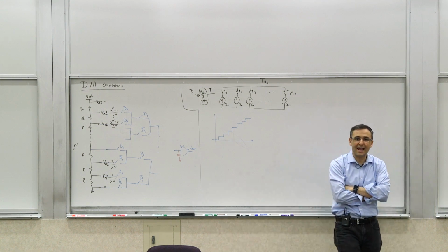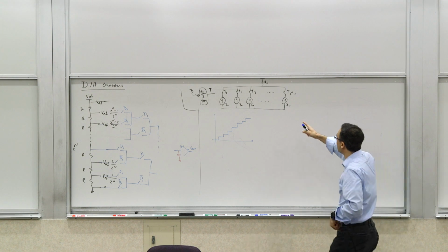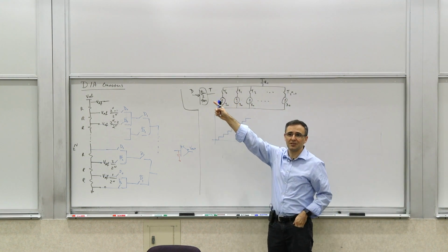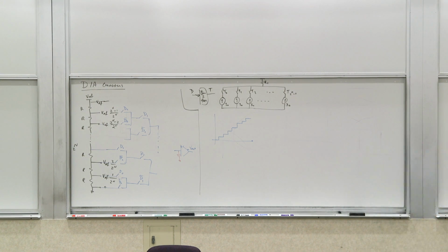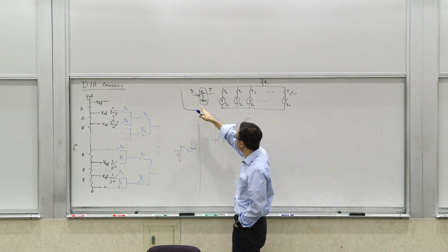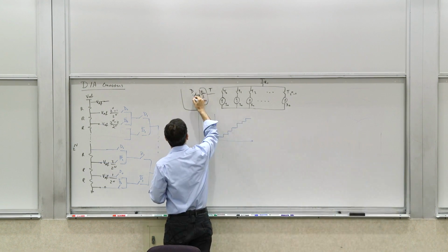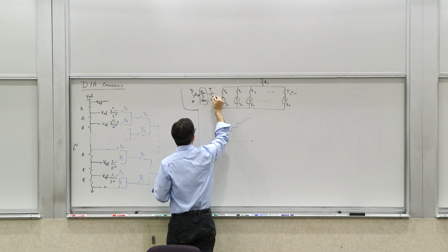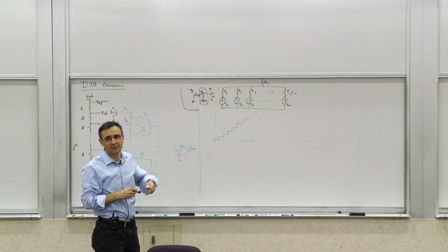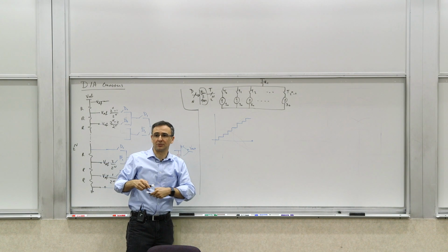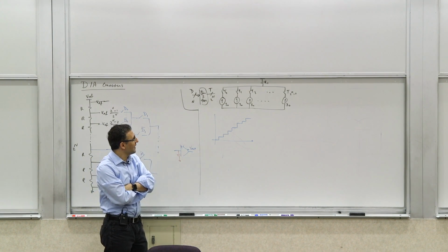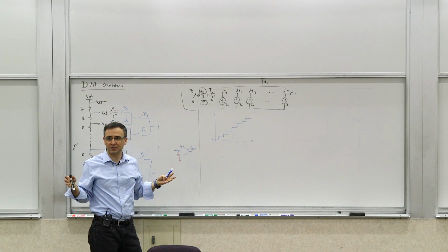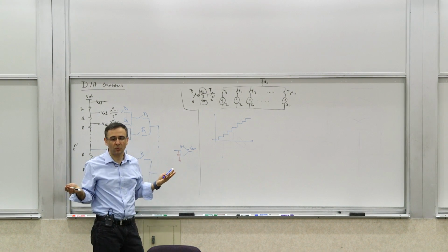More importantly, you need to wire 4,000 digital wires to these switches in an efficient fashion. That comes out of your combinatorial logic, which has 12 bits input. So in that example, this is n, but this is 2 to the n. So it would be 12 and 4,096. It can grow out of control pretty rapidly, especially the digital wiring of it.